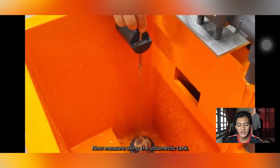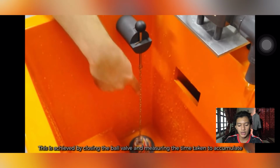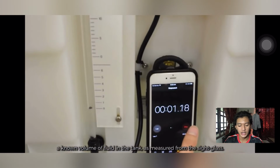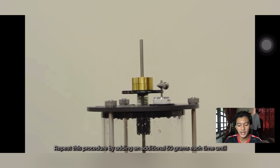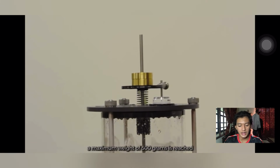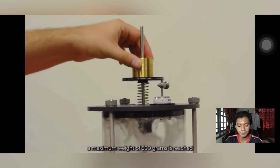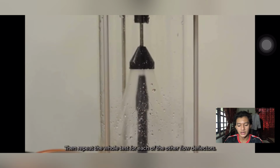Now measure using the volumetric tank. This is achieved by closing the ball valve and measuring the time taken to accumulate a known volume of fluid in the tank, as measured from the side glass. Repeat this procedure by adding an additional 50 grams each time until a maximum weight of 500 grams is reached. Then repeat the whole test for each of the other flow deflectors.